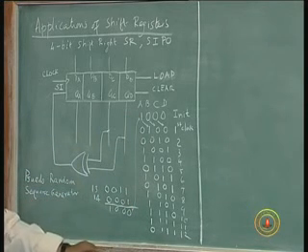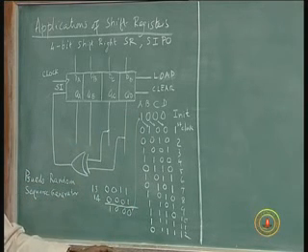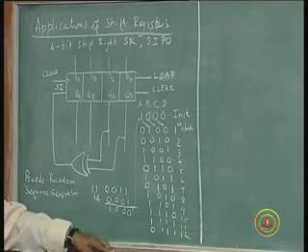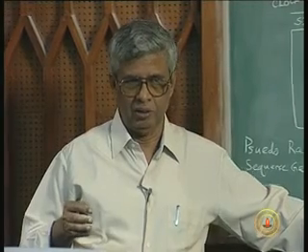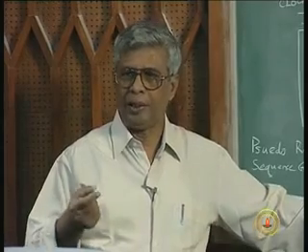If the initial pattern is different, then we will have a different sequence, again of 15. So it is not completely random. You know that after 15 it will be repeated. So that way it is pseudo random. Pseudo random means semi random. It is not completely random. You know there are 15 patterns going to come, and if you know the initial pattern you can guess the other patterns. So that's why it is called pseudo random.